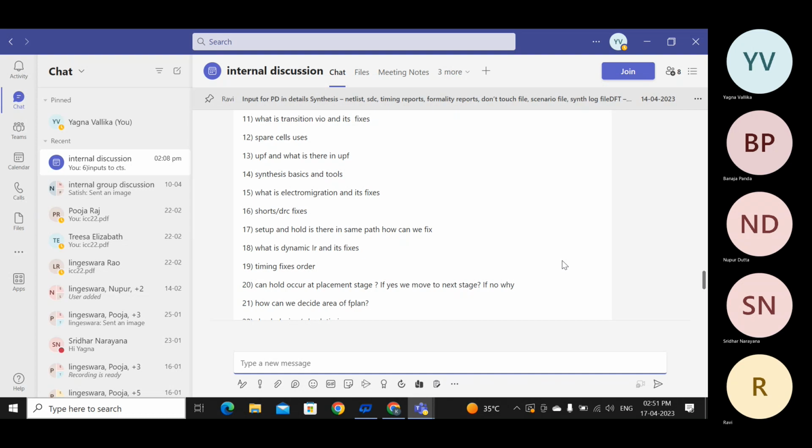And what would constitute spare cells: there should be at least one inverter in any spare group. In case flops are required, you would add maybe, but I want to add one NOR gate, one NAND gate, one inverter. These are all basic things so that you can construct any other cell required. Yes? 2x drive, 1x drive, low drives you can keep. Okay. So decent things will be there. Okay. That's about it.